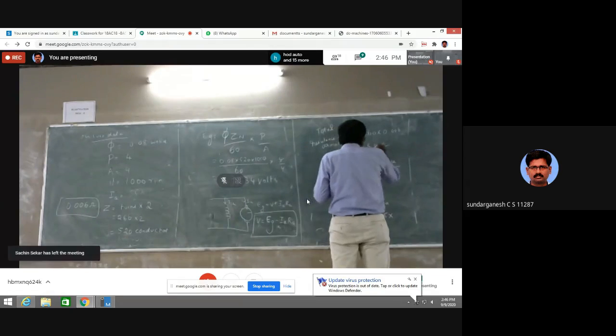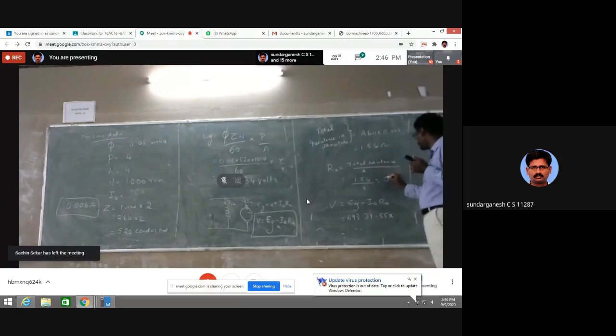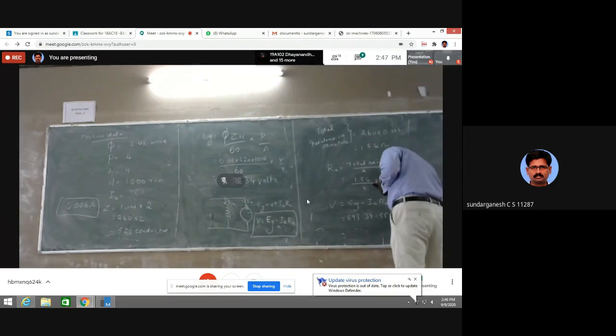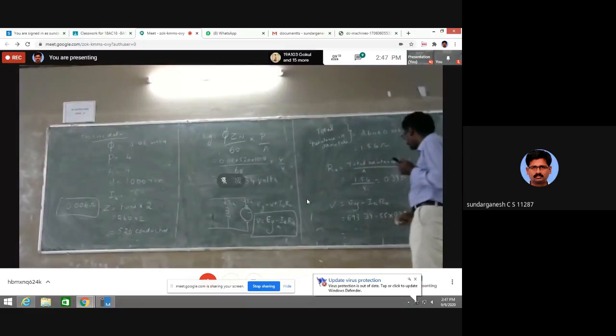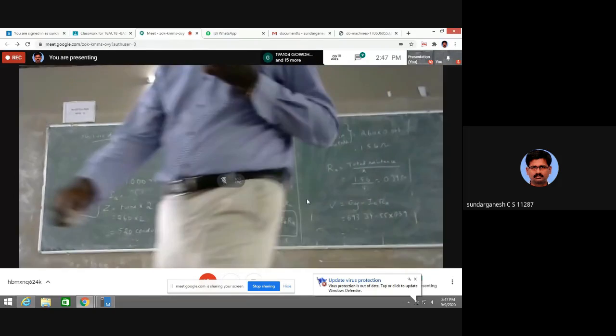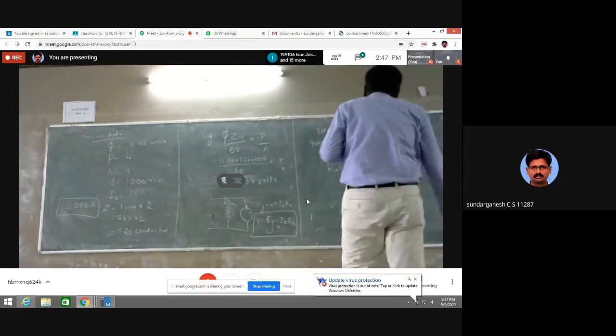Here 1.56 by 4, you get 0.39 ohm. So RA is 0.39 ohm. So here you have to multiply by 0.39. So you get a value of 671.89.